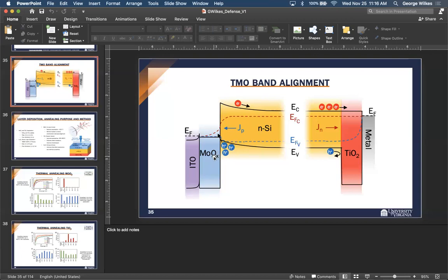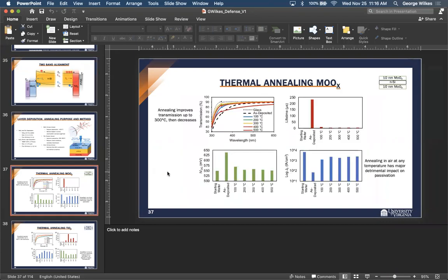Again, molybdenum trioxide is an insulator, which would not be good for carrier selectivity. It'd just be like a barrier. But molybdenum dioxide is sort of a conductor, so that's also bad. So we want a ratio in between, but I don't know if anyone's really spelled out the optimal stoichiometry for this type of layer. So we'd look at that. Obviously, we have the method of measuring passivation, but I think hopefully that would help.